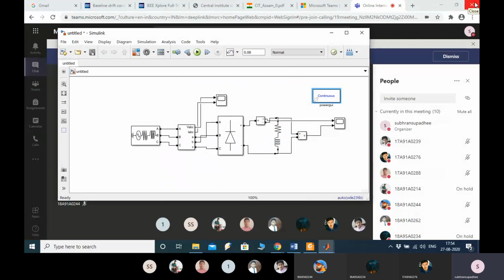I am giving some of the stuff, explaining some of the stuff. Rectifier, I have given three-phase rectifiers, single-phase rectifier, three-phase diode rectifiers only. These are uncontrolled rectifiers because with the diode, you cannot control the forward biasing and the reverse biasing of the diode. That's why it is called an uncontrolled rectifier. Next class, if we are comfortable, we will go to controlled rectifiers.